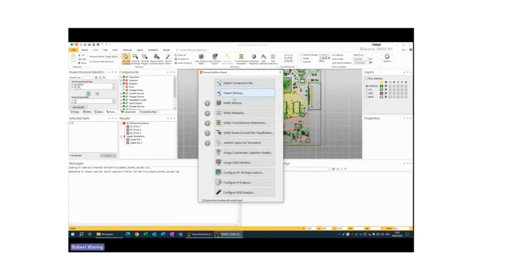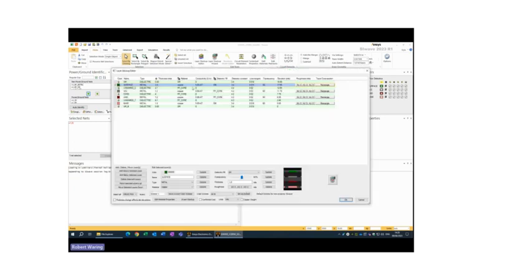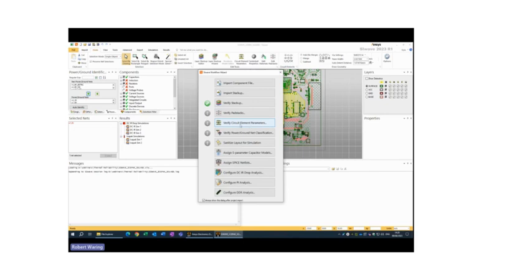This is the workflow wizard. This is how, after you've imported, you verify your stackup. You can check all of the layers, make sure that the materials are right, the thicknesses are right, etc. You verify all the pad stacks, make sure your circuit elements have come in properly. You can do your power and ground net classification. We're going to go straight to the power drop analysis first.